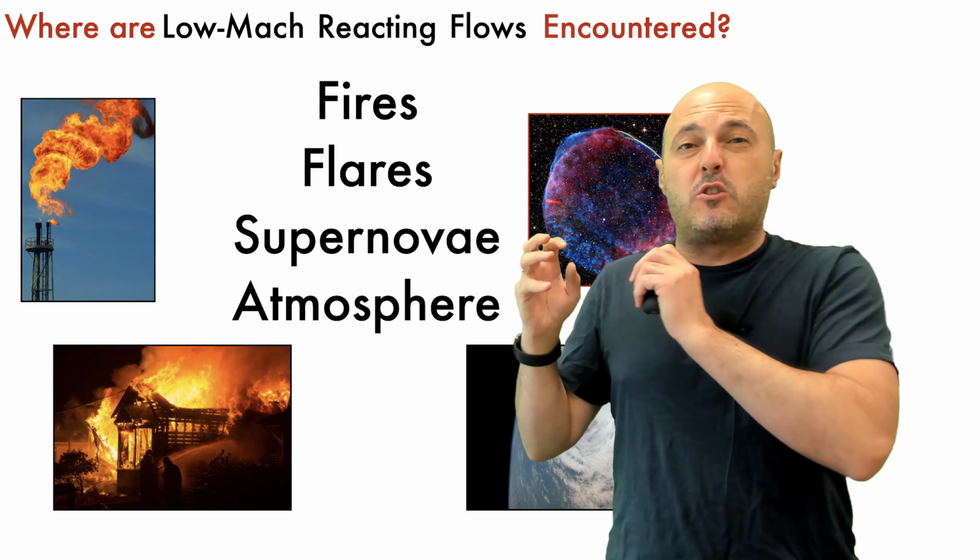Gas dynamics are the true continuum equations of any fluid flow. So when you consider real flow, you got to start with the full gas dynamics equations. These are the Navier-Stokes equations, so continuity, momentum, and energy equation, and an equation of state. Okay, and whatever else you might be tracking, but those are the foundations, we're going to call them like the true fluid flow equations.